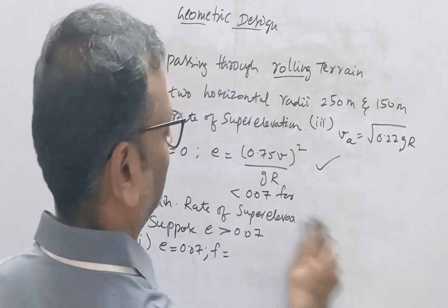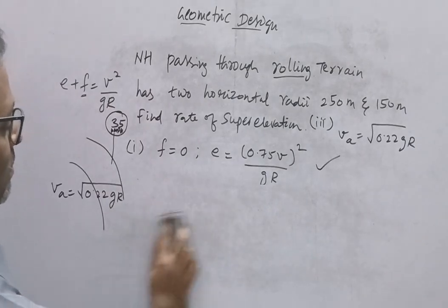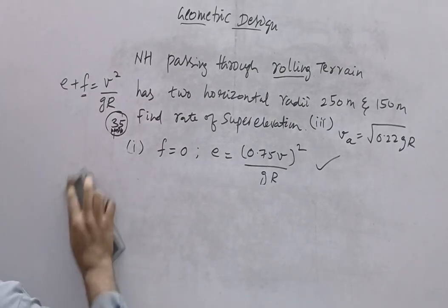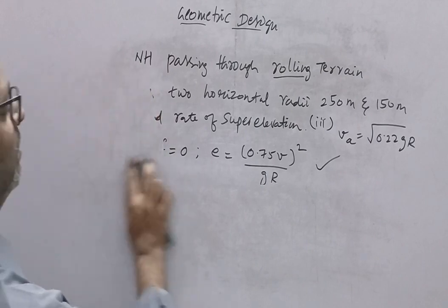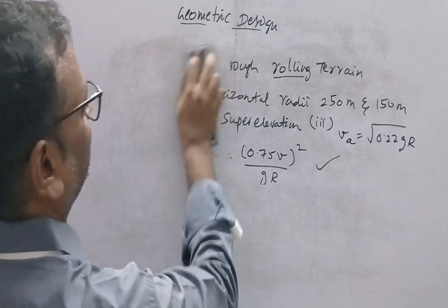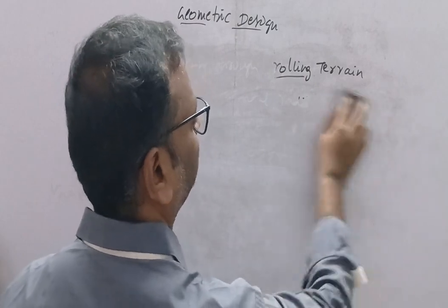Highways are generally constructed as high type bituminous roads, that is 1 in 50 for high intensity of rainfall regions, 1 in 60 for low intensity regions.